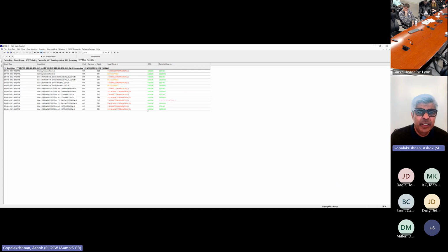So you have a lot of cases where the protection system behaved correctly, but you also have many cases, wherever you see these reds, where it says miscoordination, that is a problem because some other relay operated and removed some piece of equipment from service that it should not have. And you also had some CTI violations where a backup protection device was too close in time to your primary protection device. And that is something we want to avoid as well.